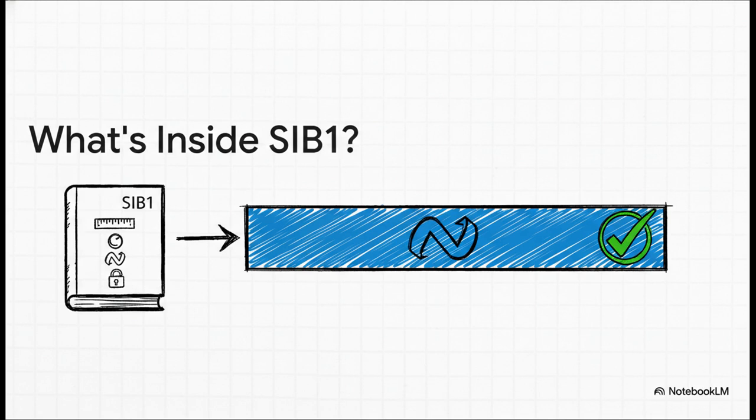This is really the aha moment in the whole process. Because remember, up to this point, all the phone knows is the location of that tiny little SSB. It has no idea how big the actual network channel is. SIB1 is what finally reveals the whole picture. It lays out the channel's precise start and endpoints, which mobile operator it belongs to, whether the phone is even allowed to connect, and how to find any other system info it might need.